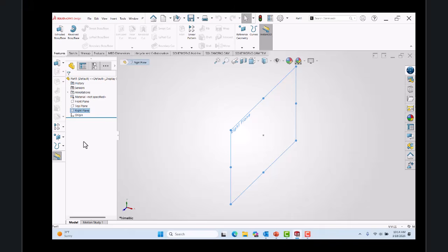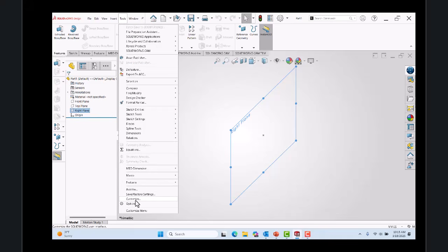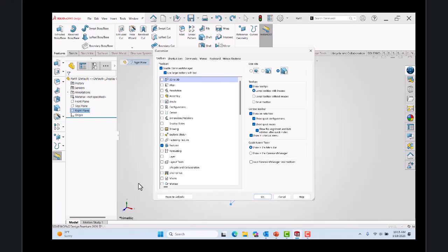As an educator, you may have this graphics window displayed in your classroom and you want to review a part. There are a couple of settings that I really like in the classroom, and I'm going to show you those. If I select on Tools and I go all the way down to Customize, I'm going to look at the toolbars. And what I have selected, this is not the default, is use large toolbar buttons. It's easier for students to see in a classroom.